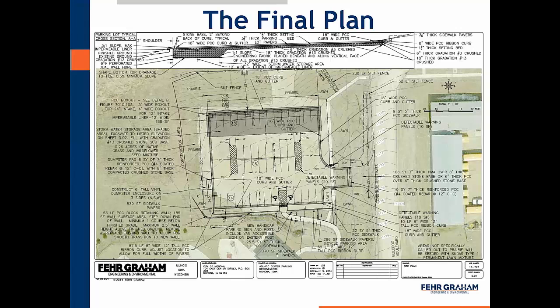And then onto the stormwater portion, everything you see there in the parking lot and the sidewalk just on the southerly or bottom edge of the parking lot is permeable pavers. So those are infiltrating every drop of water that falls onto that area. And we'll get into the details. We've got a bunch of construction photos that you'll really get to see how this all works. But the permeable pavers are made out of a high-strength concrete, so we're not getting any infiltration through the paver itself. It's all through the joints that are between the individual pavers.